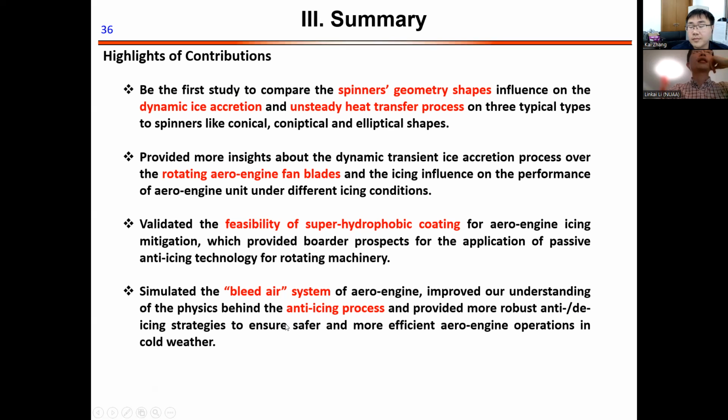Now, the last part is the bleed air system. We find that the mass flow rate and the temperature are two significant factors for the anti-icing and de-icing strategies. So if we adjust these two factors, the aero-engine can find a more efficient operating condition in cold weather.